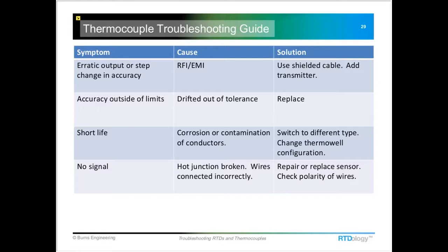Some of the metal foundries where they're measuring molten metals, or maybe it's an extrusion process where you're heating up a block of aluminum before it's going through some kind of drawing process, you're going to be replacing thermocouples quite frequently, just because that high temperature causes them to drift fairly quickly. They get contaminated, and then their output changes.